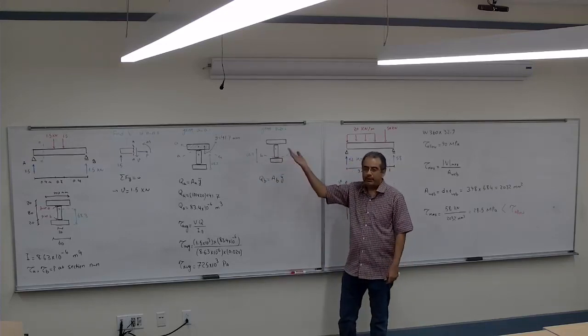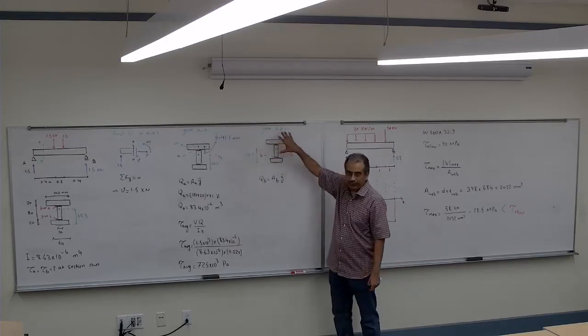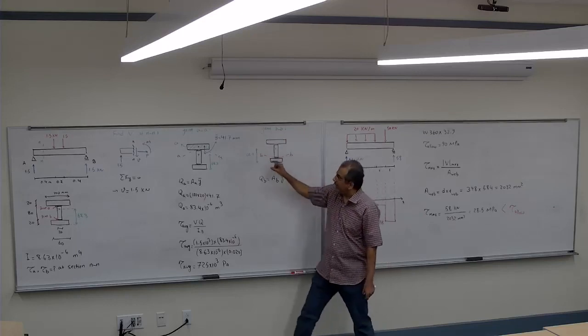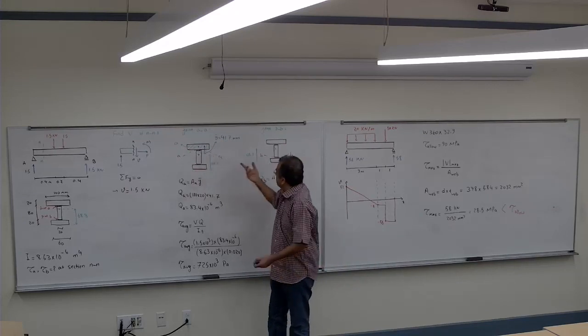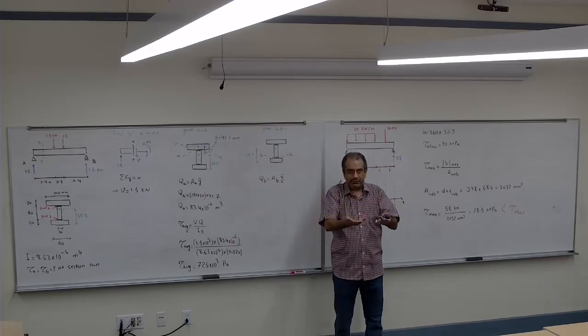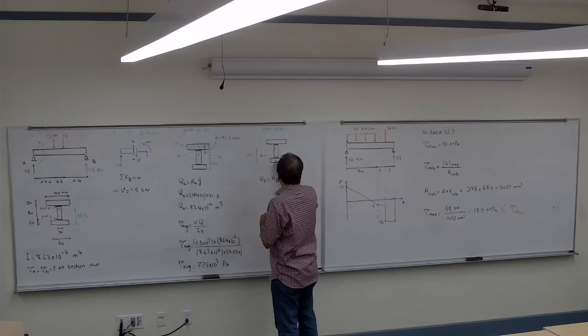The Q for either of them is equal. It doesn't matter. If you calculate the Q for the T shape of the top, it would be equal to this small one. The same here. So usually, when you cut it, look at the area above it and the area below it, and see which one is easier to work with. Here it's easier to work with the one at the bottom, so I'm going to choose this one, and this is going to be the Y bar.